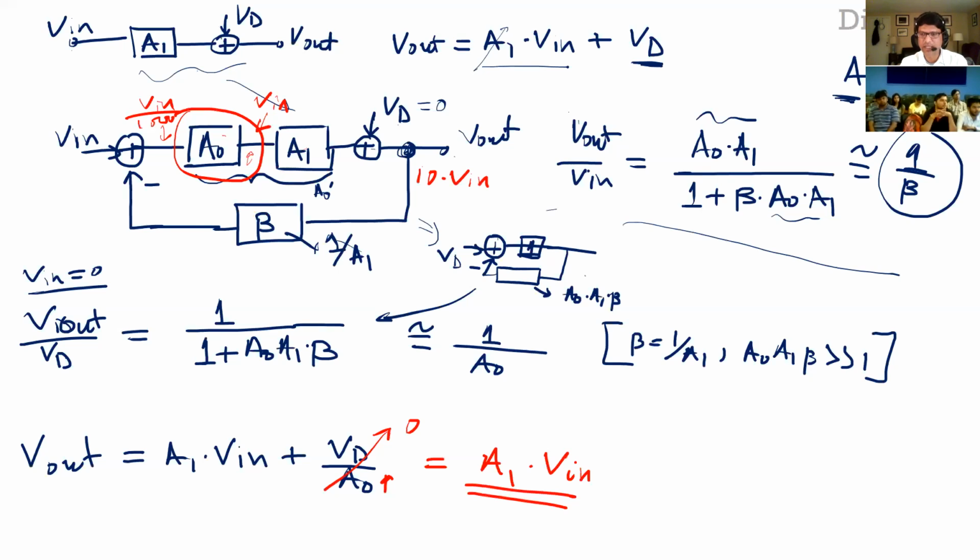Now this doesn't have to be two amplifiers. It can be just one amplifier, but this explicitly shows you that you improve distortion by just having a high gain, and usually your distortions are at the output of the stage. If it is at the input stage, you can't help it. But because you have this high gain, the input you see over here, this error amplifier, is tiny.